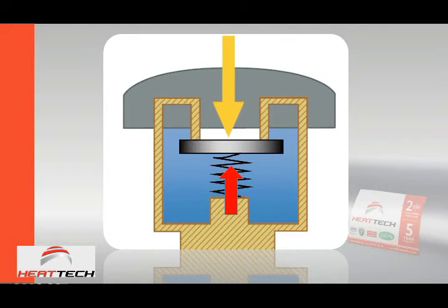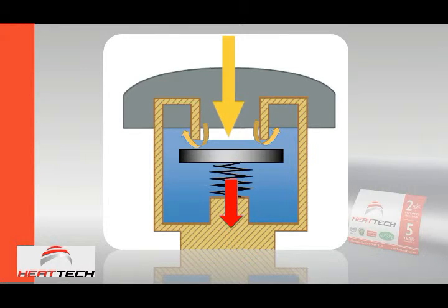So no air can escape, your water pressure is safe, everything goes fine. But what happens now if the water pressure reduces? In other words, you now have a loss of pressure on your inlet line. Somebody opens the tap on the outlet side, and suddenly it is gravity that tries to suck the water out. It can't be fed from the supply line because there's no more pressure. The only pressure is generated by the height in the water.